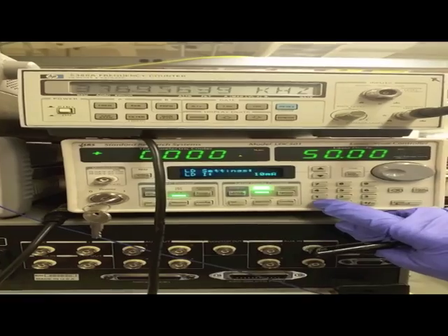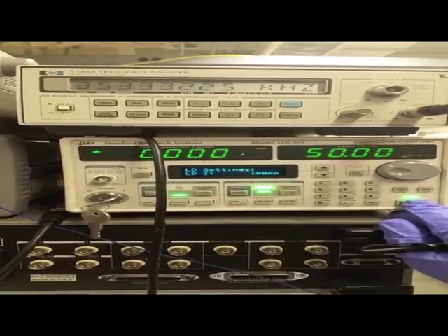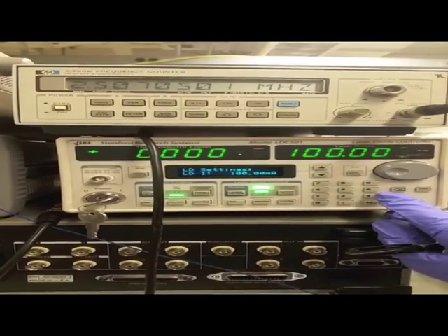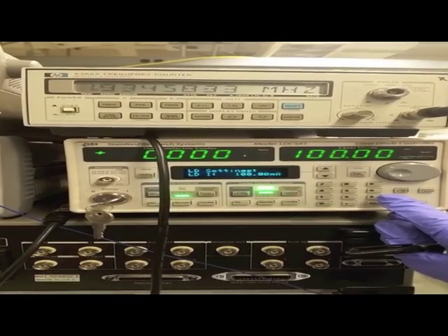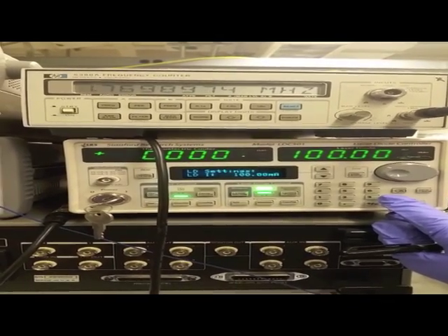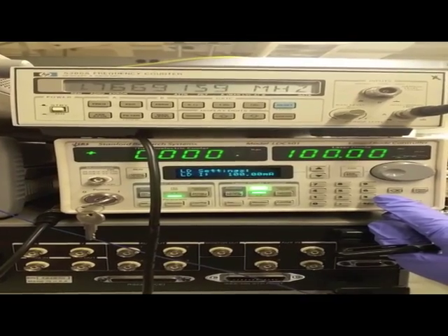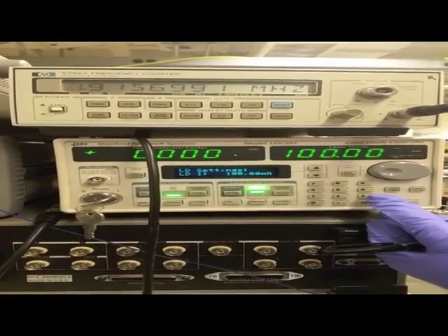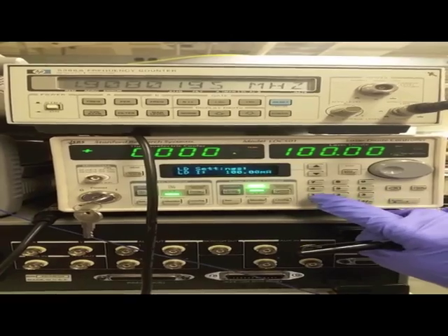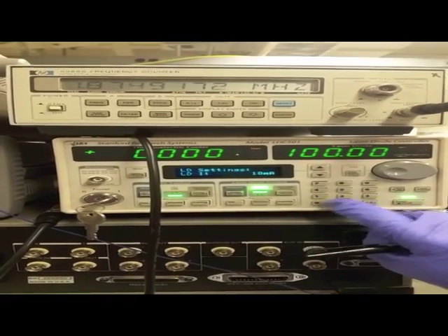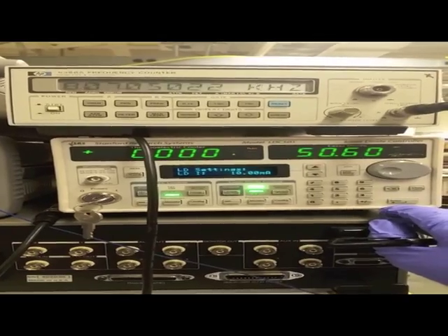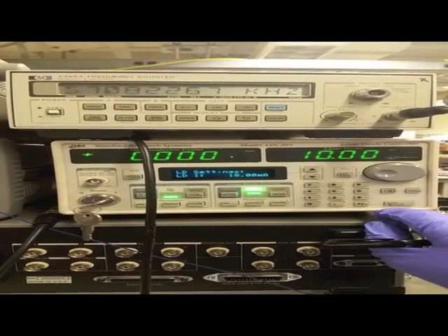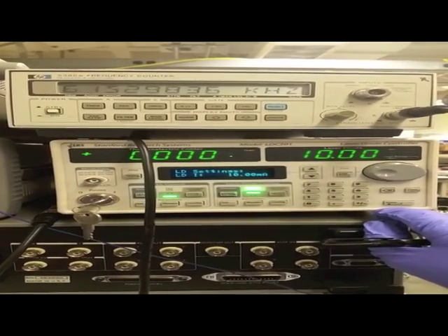To further quantify the frequency output of individual pixels, we connected the outputs to a digital frequency counter, shown on the top of the screen. As you can see in the middle of the screen here, we are adjusting the laser intensity by adjusting the current input to the laser diode, and you can see the frequency increase with increasing current. Right now we are at 100 milliamps of current, and the frequency is in the vicinity of 2 megahertz. By decreasing the current to 10 milliamps, you observe the frequency fall to 6 kilohertz, thus showing the shift in frequency with varying intensity of the laser diode.